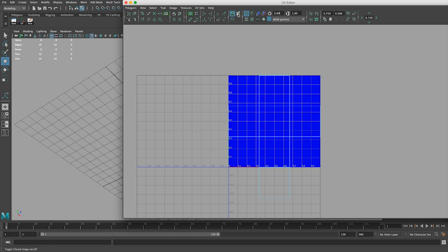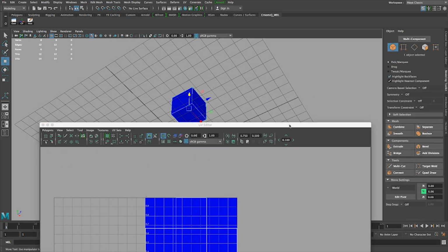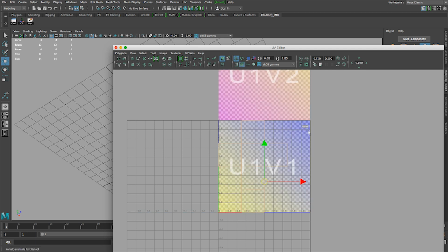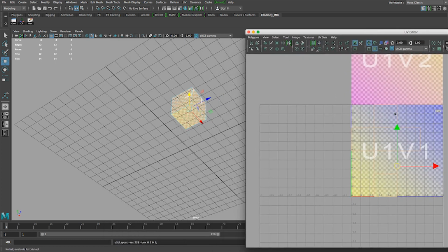And then I will just do optimize again from Maya to see. If it doesn't work, it means that you're in some kind of mode. We need to be, let's say, in object mode. And then we click here again. And it fitted. So you saw the squares became smaller, less resolution. But okay, we have one UV map. Let's press on this checkered, what we tried before. And as you can see, I see the squares.